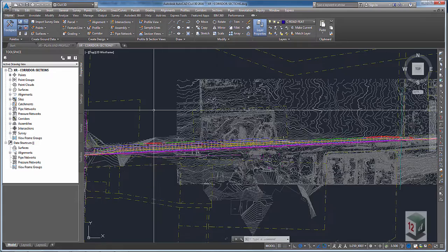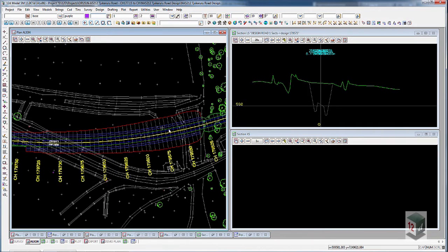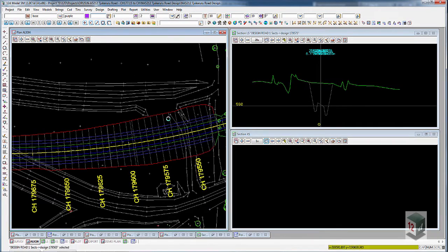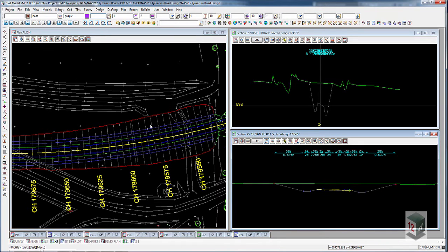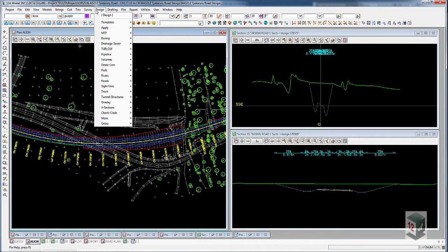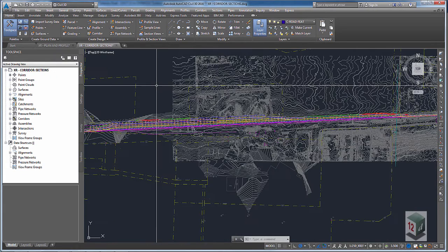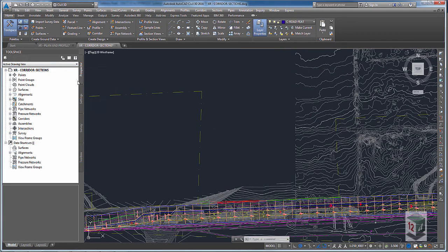Sample lines in Civil 3D are just different intervals of the sections along the road, and 12D does the same thing. At the moment, the intervals for mine are every 5 meters, but if you wanted to create additional section lines or sample lines, you can do that pretty easily in 12D as well by changing the interval or filtering down or creating a special change file.